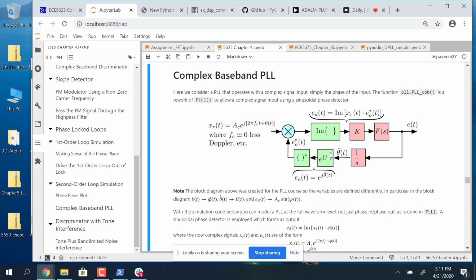And it's also very relevant for digital signal processing and software-defined radio types of applications. So in this loop, as I say here, nominally the carrier is 0, but you can freely move the signal around, up and down, by putting in a carrier frequency, and you'd be moving it up or down because it's a complex sinusoid that has phase modulation added onto it. So it has a lot of nice features. It's very much like a real phase lock loop would be in the analog domain, and definitely like a phase lock loop you could be dealing with in a software-defined radio.